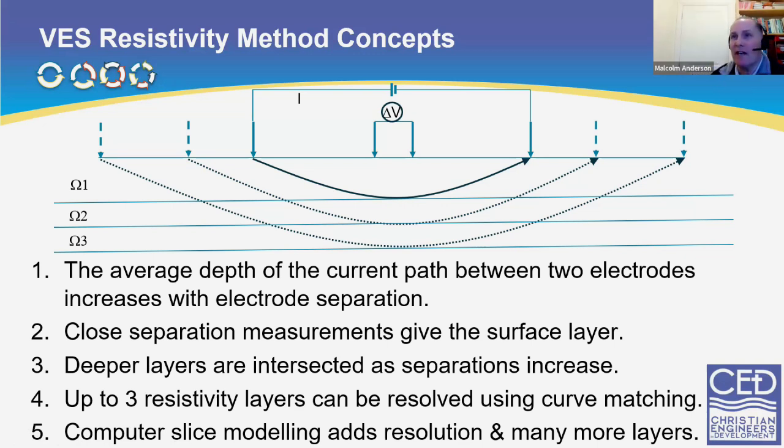The reason is that the top layer will probably be the layer above the water table. The next layer will be the water table down to the rock head, and the bottom one will be the rock head, or the unweathered zone. The weathered zone often is also quite porous, and so it's often more hydraulically conductive. So often the water level is also a function of those layers as well.